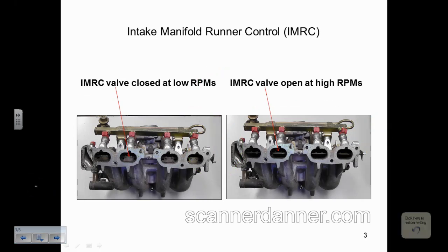Again, I'm picking on Ford here. They redesigned this again and they put a component here with a rod again, but now it has 5 wires going to it and no vacuum hoses. Of the 5 wires, 3 are a potentiometer, and 2 are a reverse polarity DC electric motor. So now they went to an electric motor to open and close the device. Again, testing that shouldn't be a problem. Power and ground for that motor function, and then a 3-wire potentiometer. Look for issues with that, trouble codes. I think you guys can handle it from there.